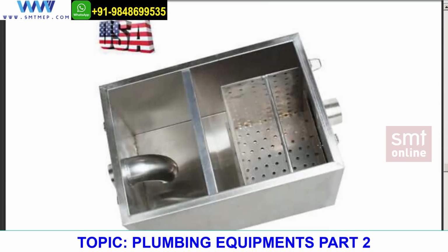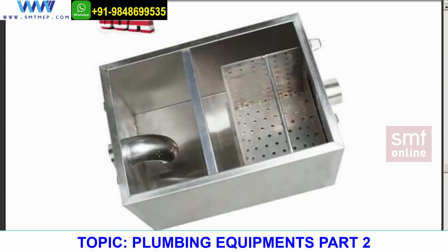Now, first of all, let me show you how exactly a grease interceptor looks. This is the inlet from my left hand side and this is the outlet. Here he is talking about the 50 GPM at the outlet. If it drains less than that, it is a grease trap. If it is delivering more than 50 gallons per minute, then it is a grease interceptor. So logically, a grease interceptor is used for high-rise buildings and the like.